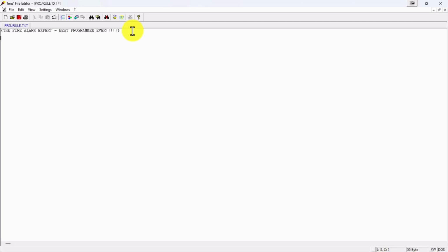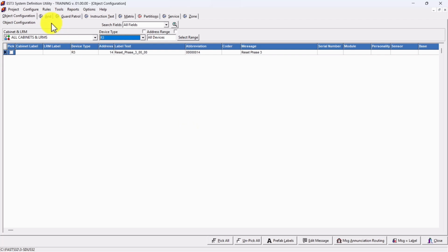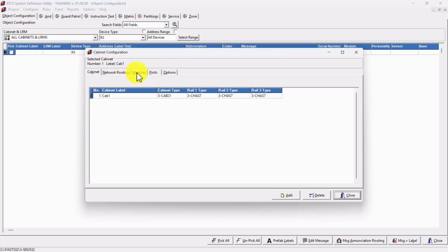So if you watch my video on how to write a rule, you will understand that you need a rule qualified. And what we're going to do is use regular brackets, and we're going to call this general alarm or smoke activation, but we're going to call this general alarm. Before we write the rules, let me just add one more thing. I want to add outputs, which is the CC1s.